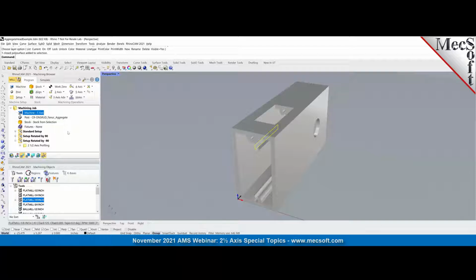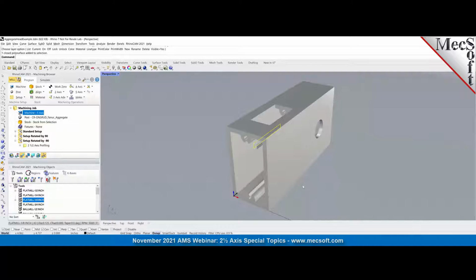They machine the electrodes, the male portion, and actually sink the electrode in. Burn it right out. Right. If it's wood, obviously you're not going to use that method. You'll have to use a smaller tool and come in maybe with a remachining operation with small tools and clean it out as much as possible. We really can't get to those sharp corners in CNC because of the radius. The physics of reality doesn't help us there. Well, that's what EDM machining is for.